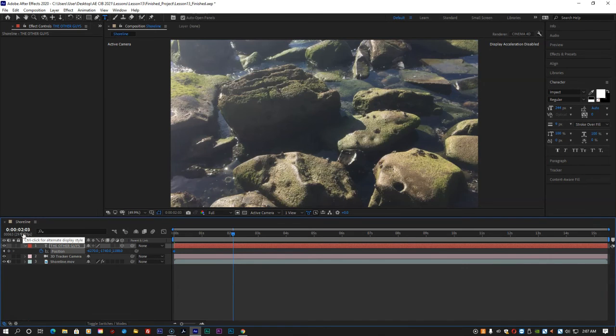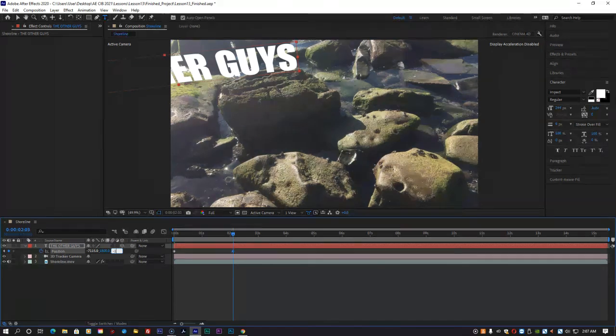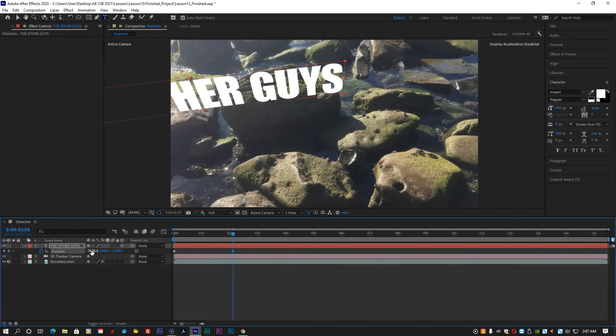and change the position property to -7115, 1800, and -1150. You can also use the selection and rotation tools to reposition it. Manually scroll through the timeline to preview the text, then close any open properties and choose File and Save to save your work so far.